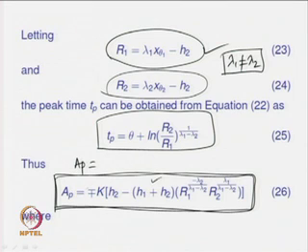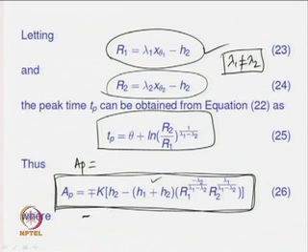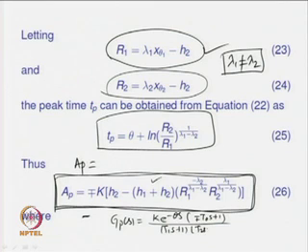Now, this negative value will be for what type of process? If you are taking a second order system with a right half plane pole. So, the negative sign, the upper one, will be chosen for a process of the form G(s) is equal to k e to the power minus theta s times (minus plus T0 s plus 1) over (T1 s plus 1)(T2 s plus 1).